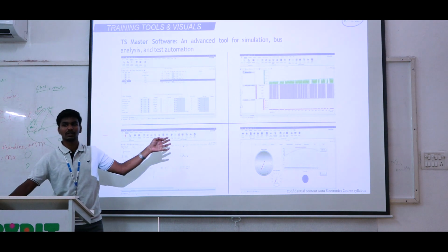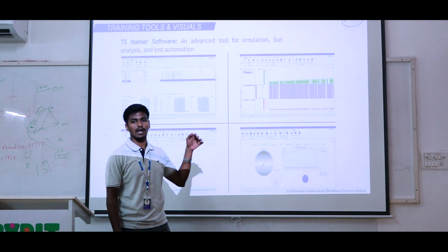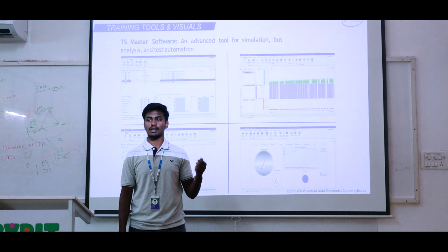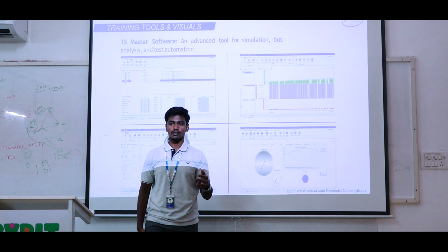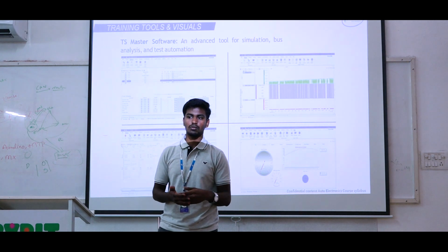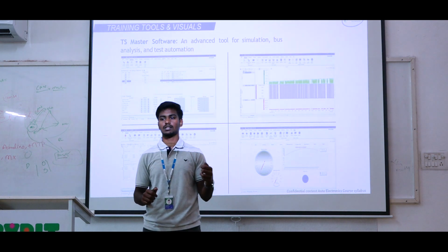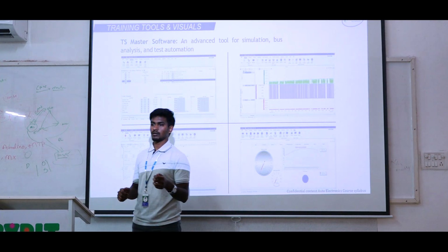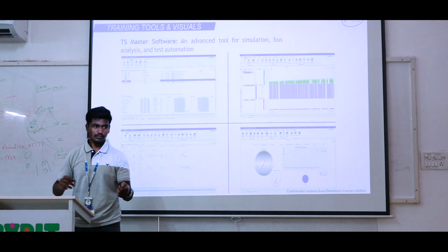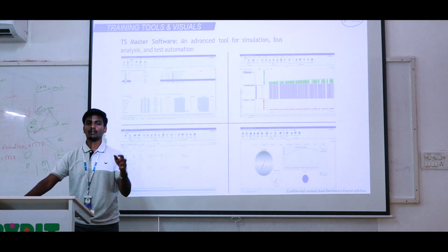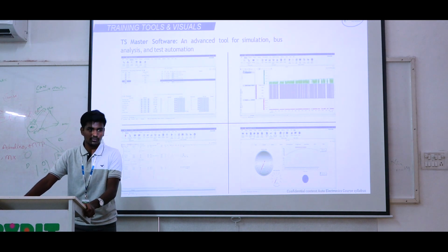Here we are going to test the communication protocol. We are going to analyze the signals, analyze the CAN messages, analyze the ECUs. We are going to find the errors and learn how to detect them. We are going to generate the report. So we write test cases for some features based on those values and our user experience. From the user interface values, we will also get the generated test report. Okay.